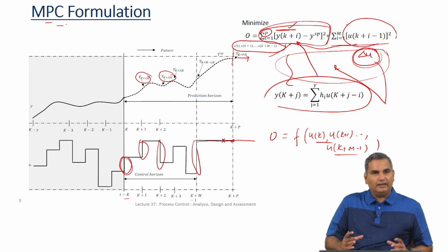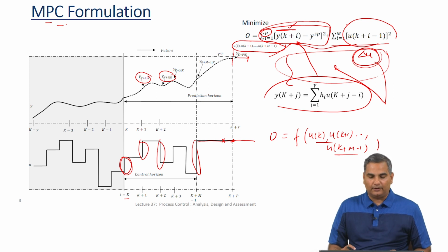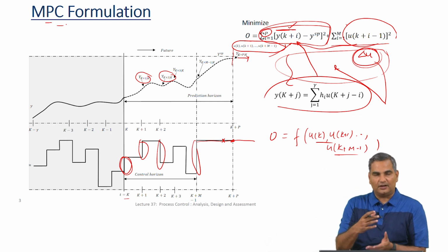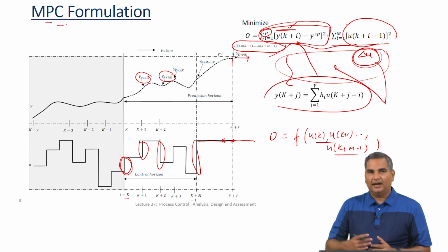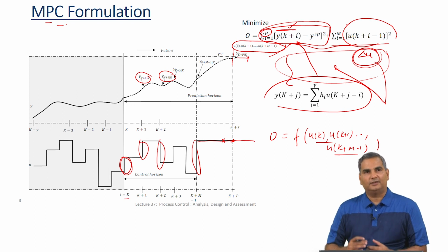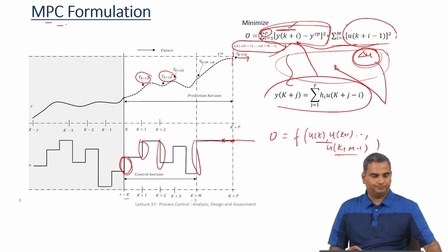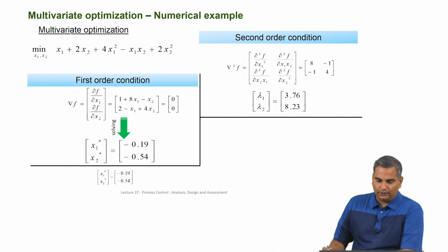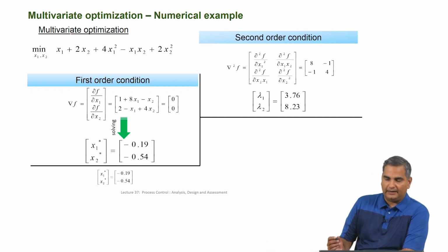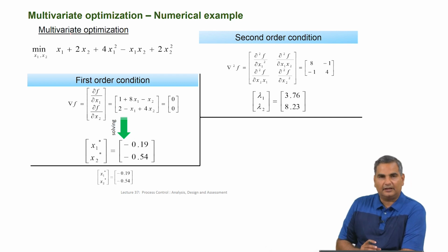So, you see how this is different from your standard PID control, in the sense that there is a prediction horizon. It is not just an immediate concern; I have a concern about optimizing over a prediction horizon, and I am explicitly using a model for doing this control. I showed this before in one of the lectures, just to bring that back here, so that we understand all of this comes together in model predictive control.